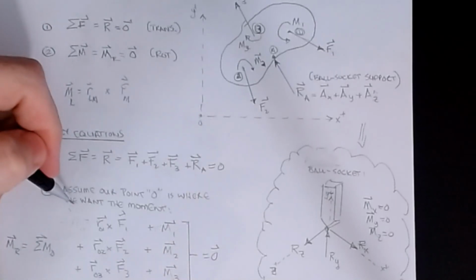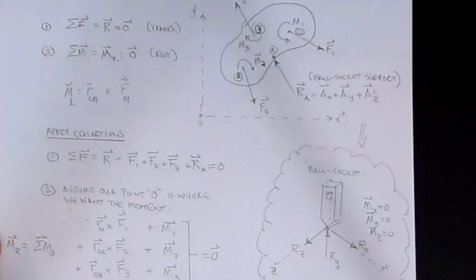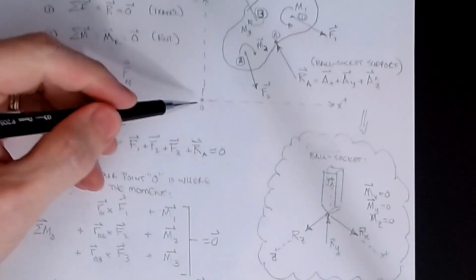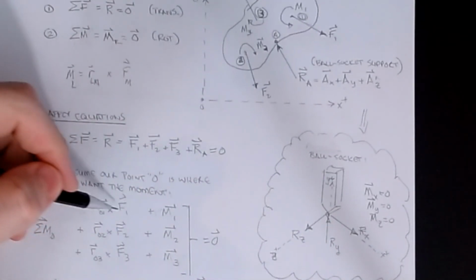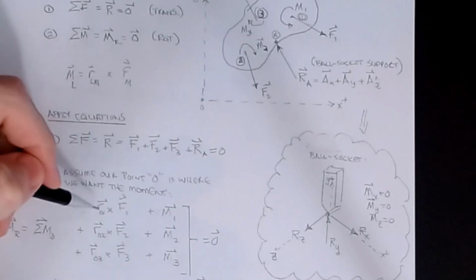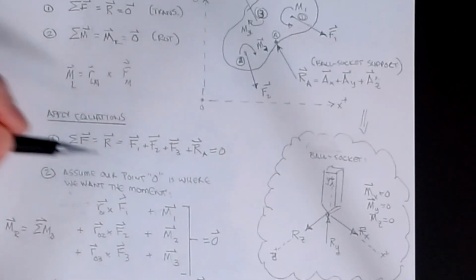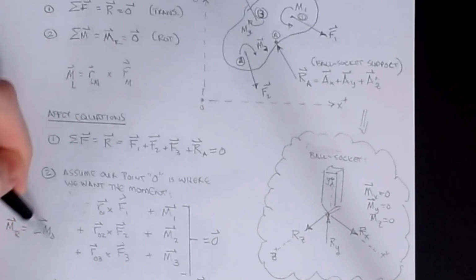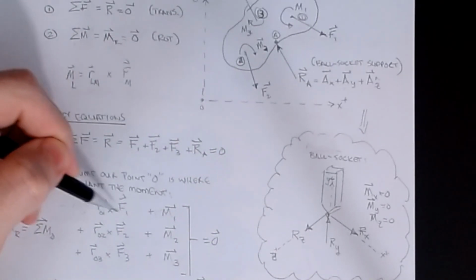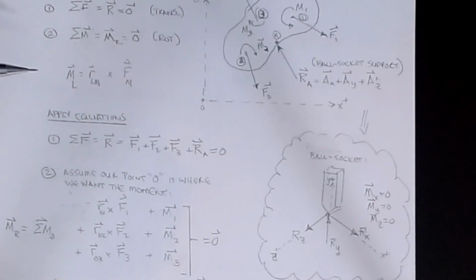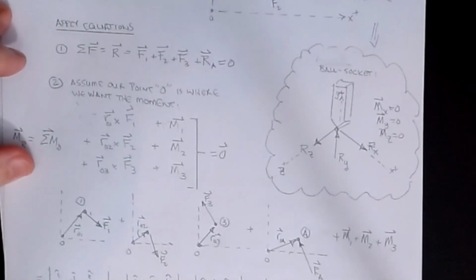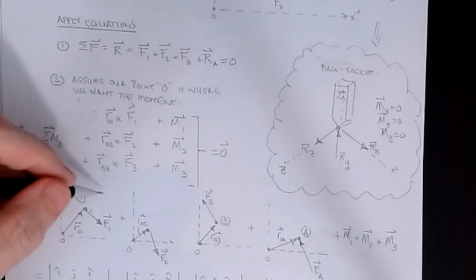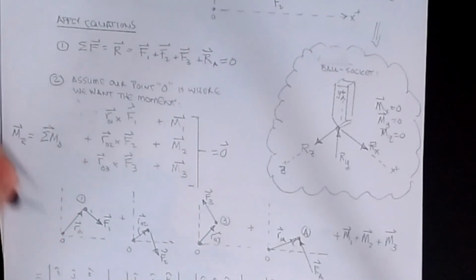So let's try that with F1 down here. For F1, I want the moment at O, the moment that the F1 force causes about that point. So we're going to do a cross product. Here's my R cross F. If I use that same idea that we just did, it's an R from O, so those two match, 2 and 1, those two match. And that's exactly what we're going to do. If I look down below, that would look something like this. Again, I just look at only the one force that I'm interested in. The rest of the object doesn't matter. The shape of the object doesn't matter. The other forces don't matter. I'm doing them one by one as I move through the system.